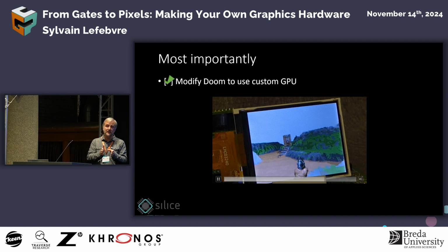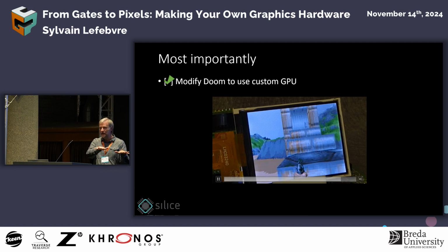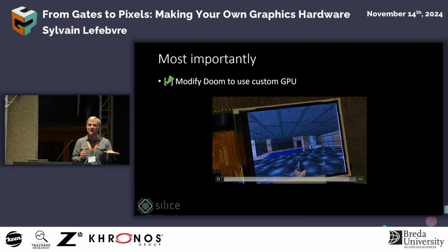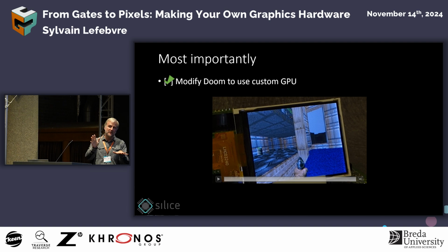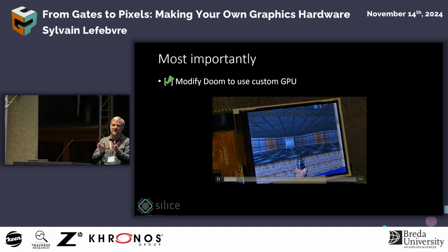Right now it's running at 50 megahertz, even though the rest of the design is 25, so having these different frequencies is a bit tricky. I should run it at 100 megahertz. I've done that in the past, but the problem is you have to rely on the tool to minimize the delays in a way that will work for the design.